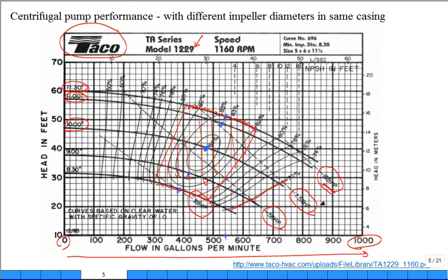bhp for brake horsepower. What motor size do I need to put on there? So if I'm going to be running somewhere smaller than that, it'll all run with a 10 horsepower motor, no problem. Anywhere on this curve is a 7.5. Anywhere over here, a 7.5 will run no problem.